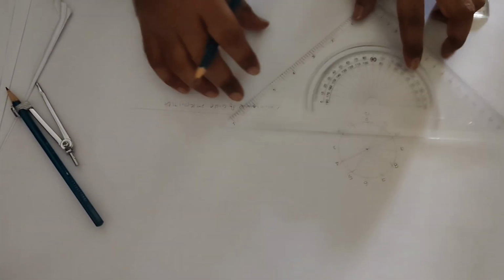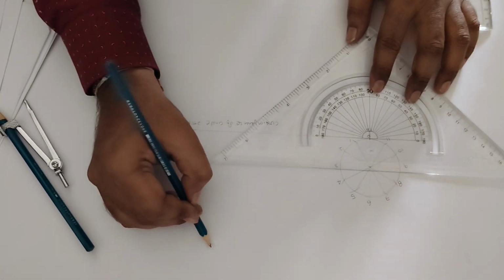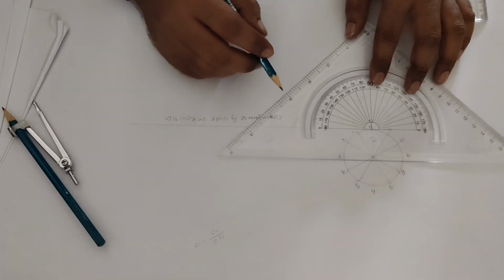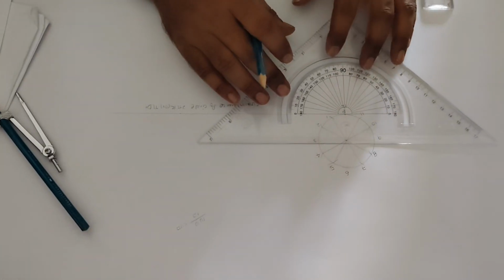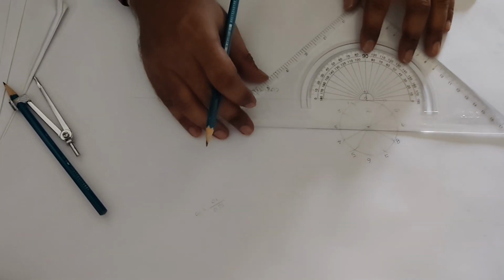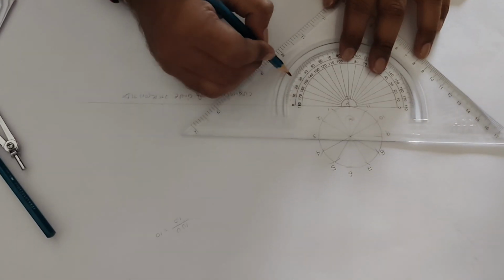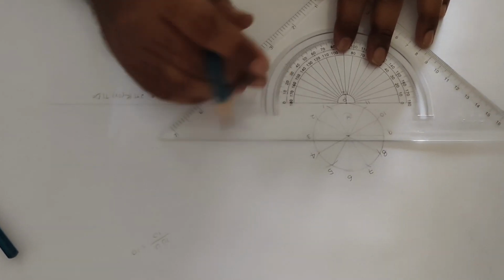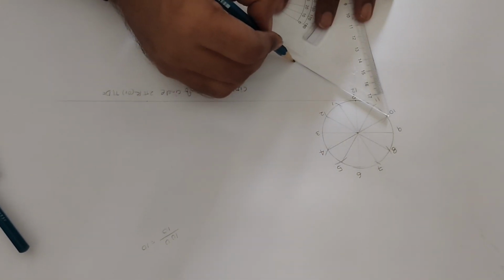How can you divide it into 12 equal parts? By using the dividing line method. If it is 100 mm, if divided into 20 equal parts, each part will be 10 mm. Then it is possible to divide into equal parts. So we are using the dividing line method, which makes an angle of 30 to 40 degrees. So I am taking 35 degrees. Okay. So by taking 35 degrees, I am drawing a line.